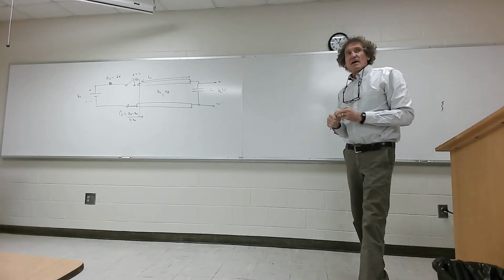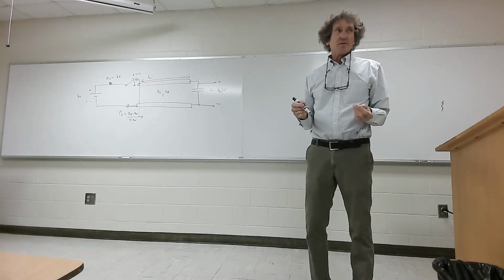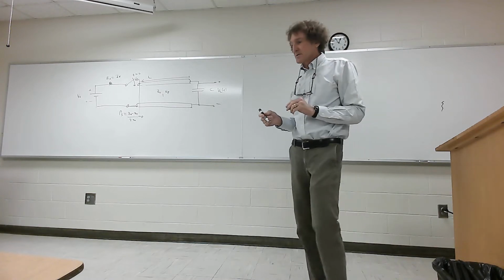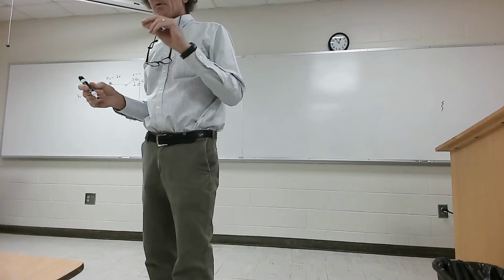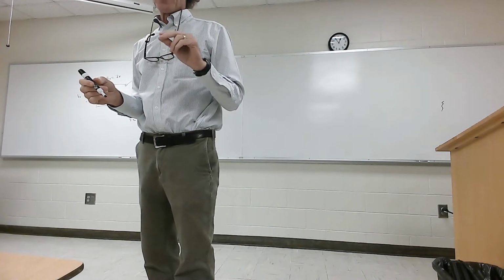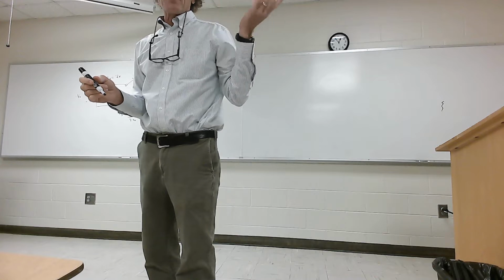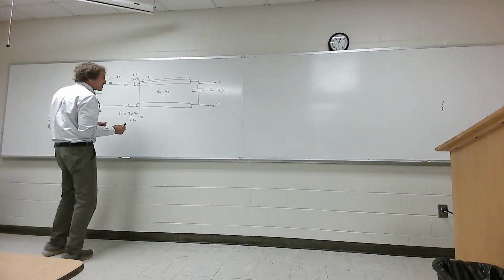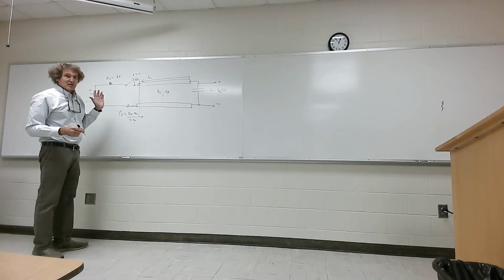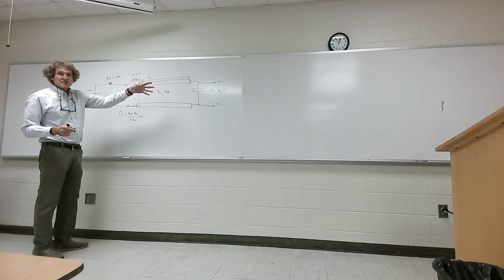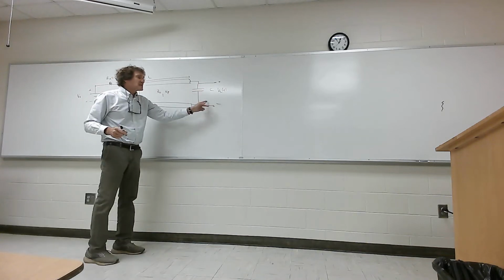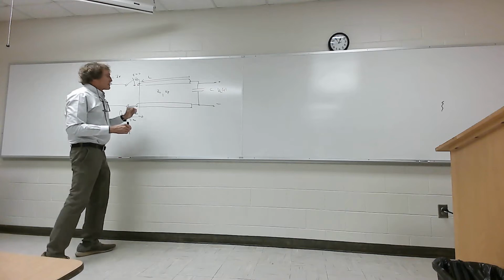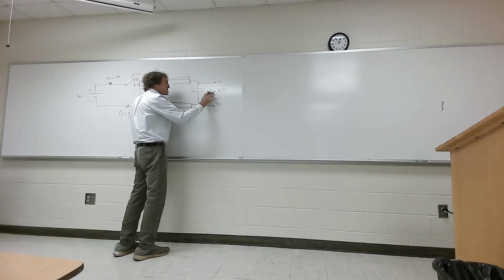By the way, everything we do these days on chip is digital, just about. You have carrier frequencies for radar and communications that are going to be sinusoidal, but almost everything is digital. It's either a 1 or a 0, 5 or 0, ideally at least. So this really looks like the input gate for a CMOS structure. Now, to be frank about it, there would really be some finite resistance there that's usually very large, but this is good.